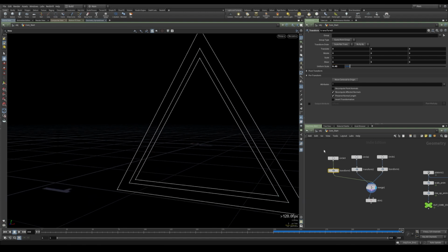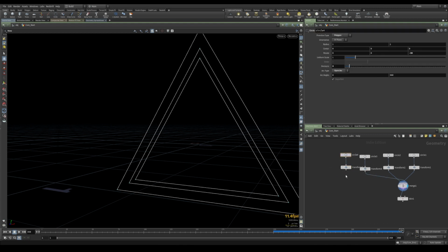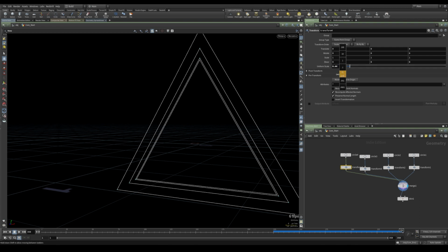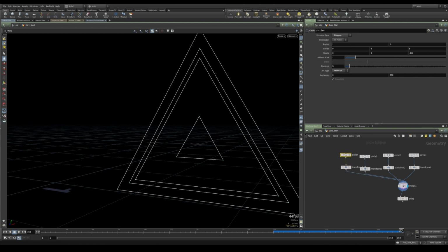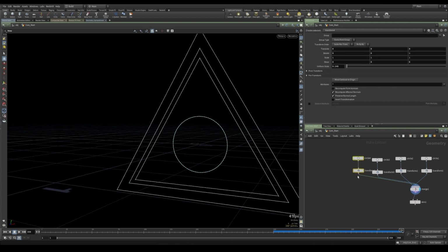Copy it again a fourth time, let's plug it, and this time we want this to be the circle section, so let's decrease the size to, let's say, 0.148, and this time we want to increase the division to some very high value, but remember we need to be a multiple of 3, so let's put 96 on it.